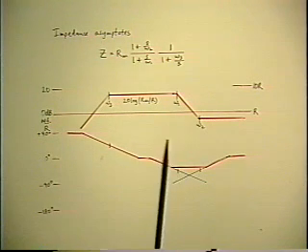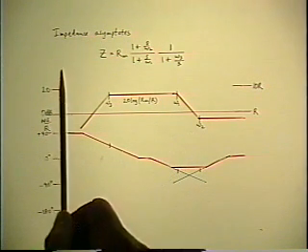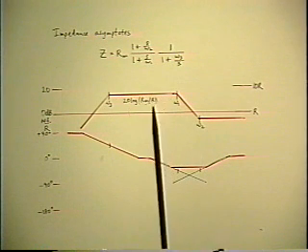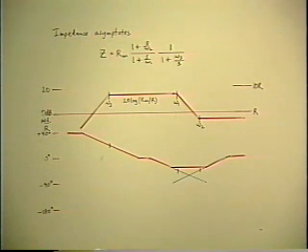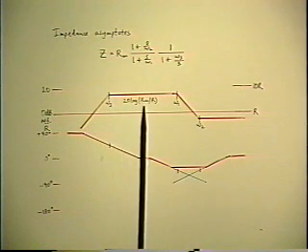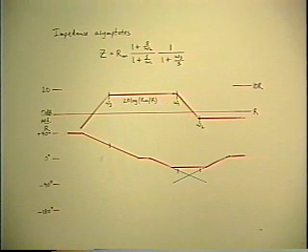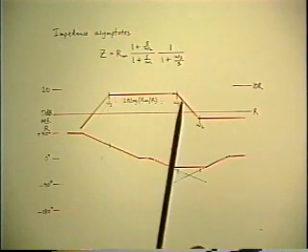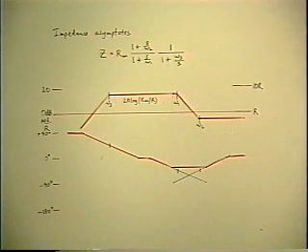Now, what sort of scale should we choose for this? Remembering that this is a logarithmic scale, or at least we'd like to keep it logarithmic. There's no point in changing the structure of the diagram just because we're talking about an impedance instead of a voltage gain. And we can still use exactly the same asymptote structure, remembering also that the smooth corners go along with it as well. The actual curve for the magnitude of the impedance versus frequency, of course, has smooth corners just as the voltage gain did. 3 dB down points and 1 dB points and so on.